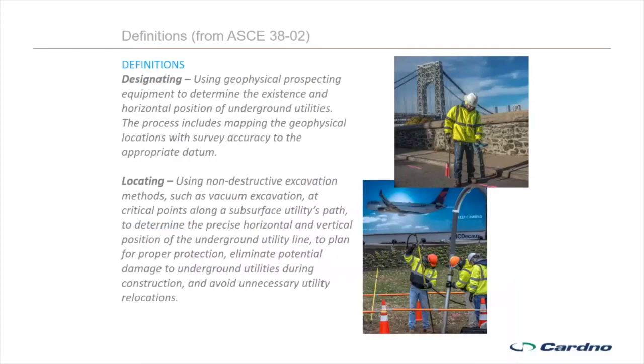Locating is a little bit of a switch from what's considered contract locating in the 811 world. Locating truly is the physical exposure of that facility using non-destructive technology, in most cases air, in some cases water. It's basically exposing that utility to get a 100% accurate 3D location of what is in the ground and where it is in the ground.